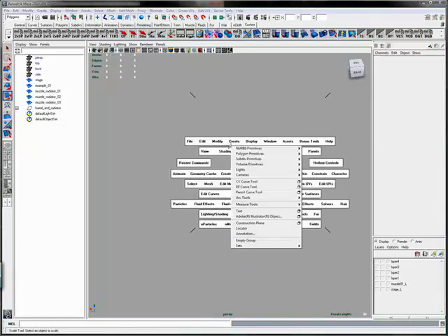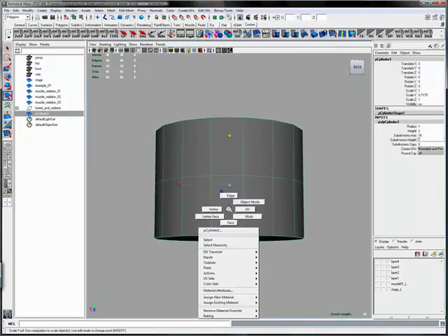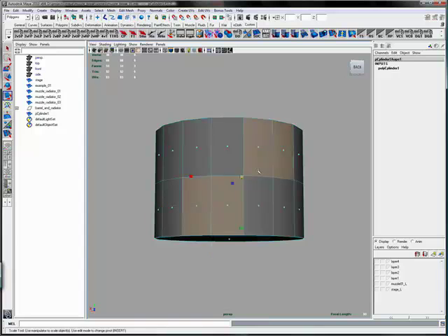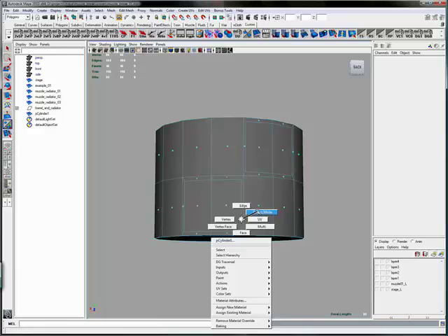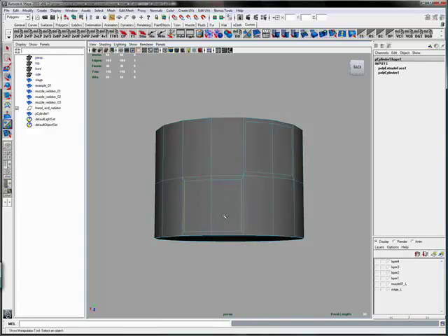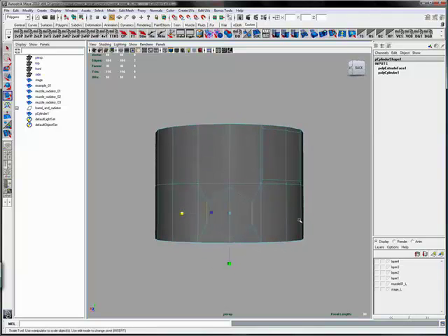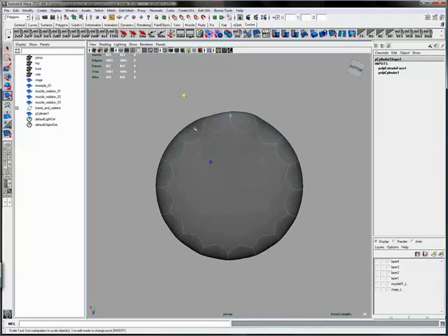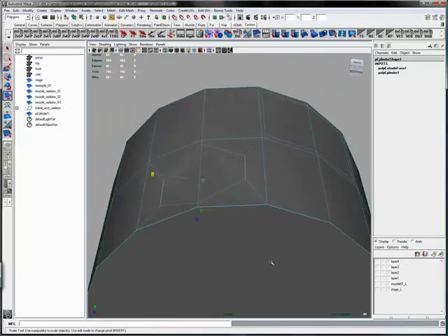So instead of an 8-sided cylinder, let's start with a 16-sided cylinder and see how that would work out. So we'll once again give it 2 divisions in height, and now we pick 2 faces for each of the circles, and now we have 6 sides, so we can make those as circular as possible and see how they'll look. And we do that by creating a hexagonal shape. We can take those 2 edges and bring them in, and just to get a rough idea, we'll do it very quickly, and you can see that it's going to maintain the circular shape around the cylinder much better.